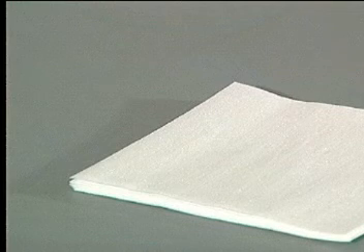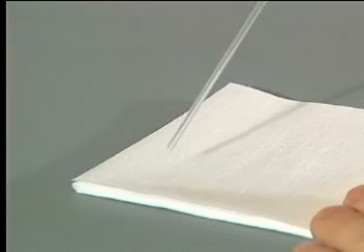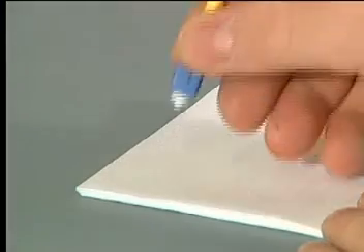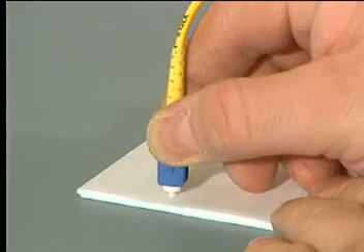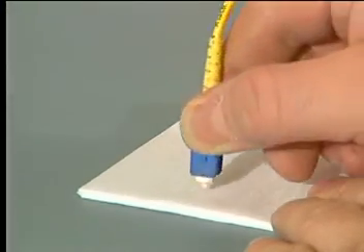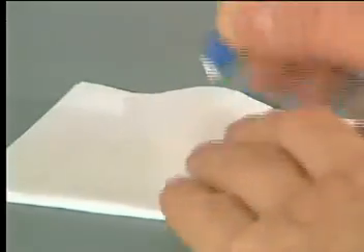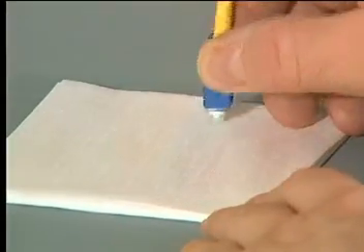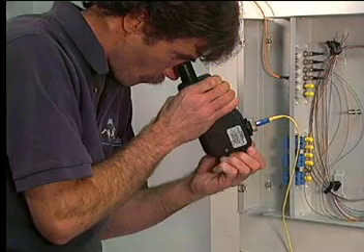Place 4 or 5 pads on the work surface to provide a soft cushion for the ferrule. Spray a small spot of solvent on one side of the top pad. Hold the connector vertically and place it firmly on the wet spot. Wipe the ferrule surface from the wet area to the dry area. Repeat this 3 or 4 times using a fresh section of pad each time. Finish the cleaning process by wiping across a fresh section of dry pad 2 or 3 more times. Then, scope the connector to verify cleanliness and repeat the cleaning if necessary.